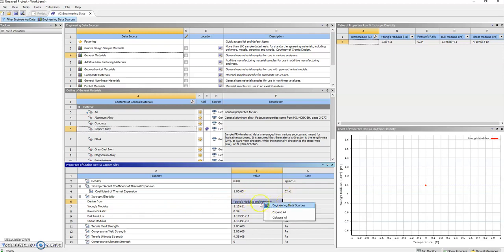So that's how it has been defined. I mean, you can create your own materials, and we will do that in later tutorials, but I just wanted to show you here. It tells you Young's modulus, Poisson ratio, and so on, but it's only based on Young's modulus and Poisson ratio. If you remember, in isotropic elasticity only two components are independent, and the others are derived from these two. Anyway, we have got our copper selected.